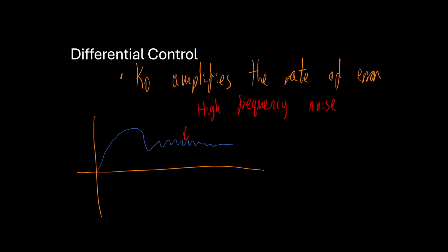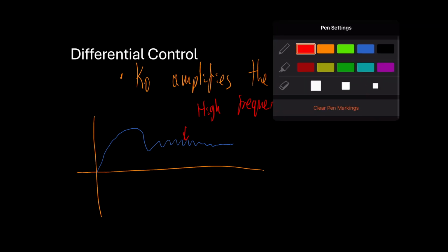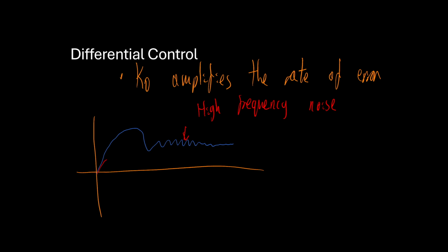It thinks it's trying to smooth it out, but in reality it amplifies this noise. So what you get instead is, it'll smoothen that part because that's alright, and then it will just oscillate. And you will not really know why that oscillation happens, but when you test your system, you need to be careful with KD, because increasing KD too much, or having KD to begin with, amplifies high frequency noise. So avoid using KD where you have high frequency noise.